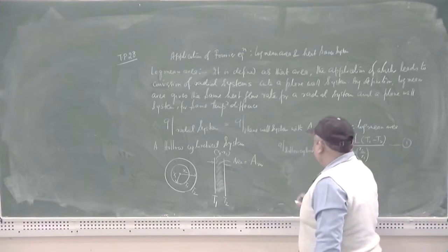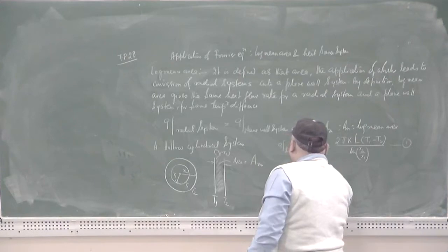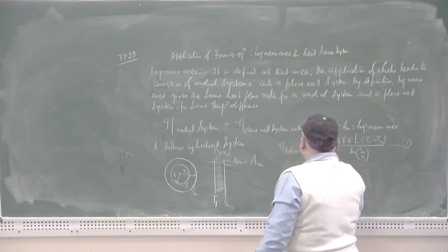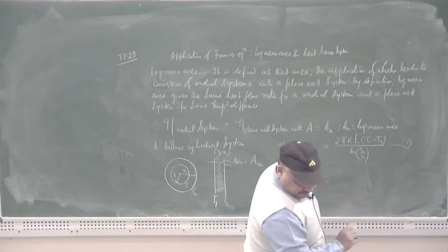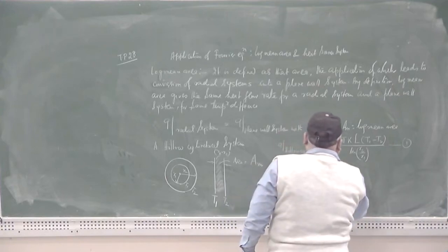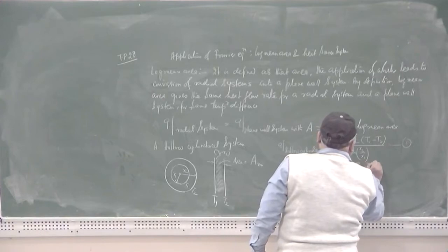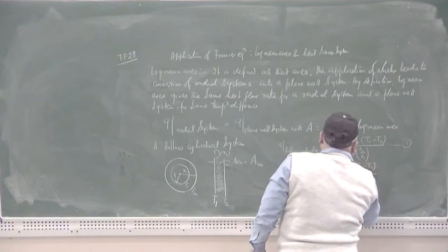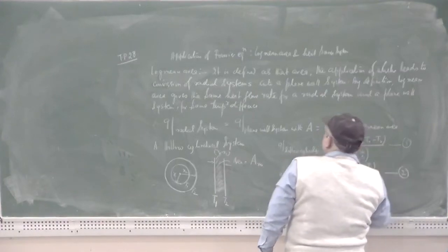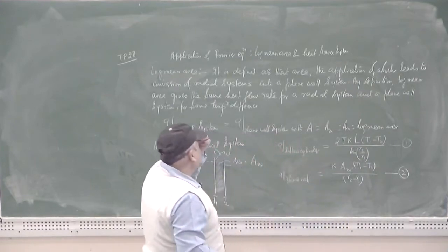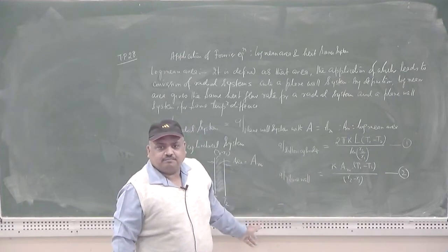And Q for a plane wall, if for the area of this plane wall I am using the log mean area, then it is equal to K AM (T1 minus T2) divided by R2 minus R1. Because we are utilizing the log mean area here, by definition these two quantities need to be equal with each other.